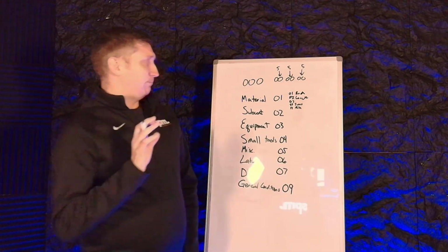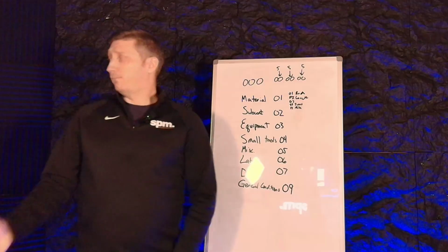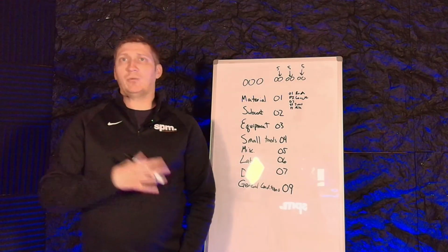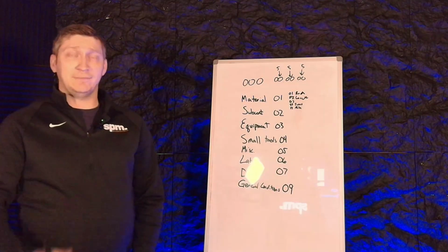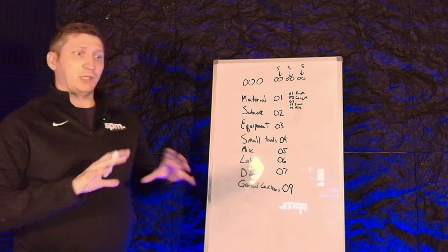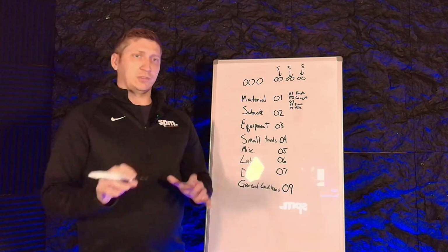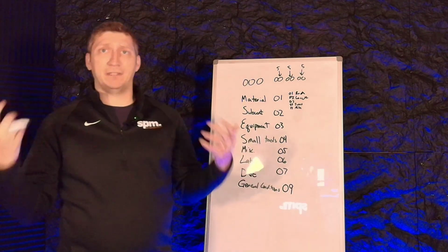What other things? Boxes. If I'm doing electrical work, if I'm going to put in boxes in the wall, they are such a small amount, depending on what I'm doing. That's where I'm going to cost code them to. Versus EMT, I'm doing so much EMT or so much wire that I'm going to track that as a big bucket to track against, maybe per floor, because electrical is a little different. But that's how I want to think about these.